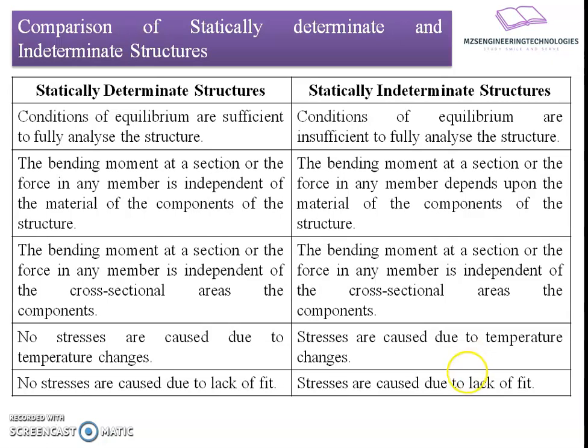nearly all the degrees of freedom are going to be locked, and in the locked degrees of freedom, the member will be subjected to either compression or tension due to increase in temperature or due to stretch or pull applied to have fitting. In case of a too short member, or in case of a too long member, the member will be subjected to additional compressive forces. Thereby additional forces develop in the member, and we have to address these additional forces